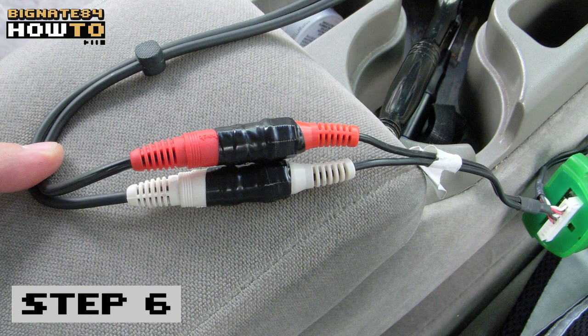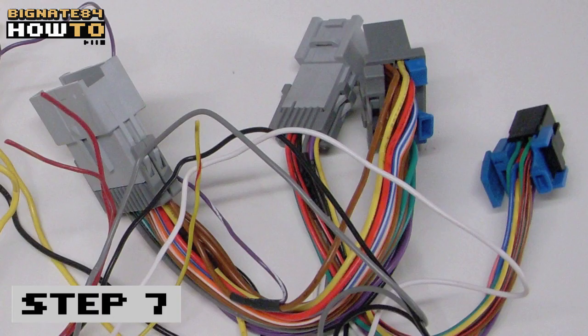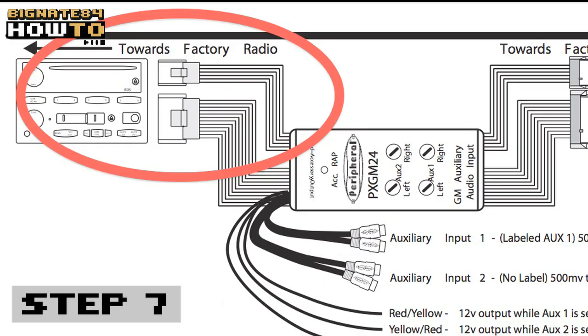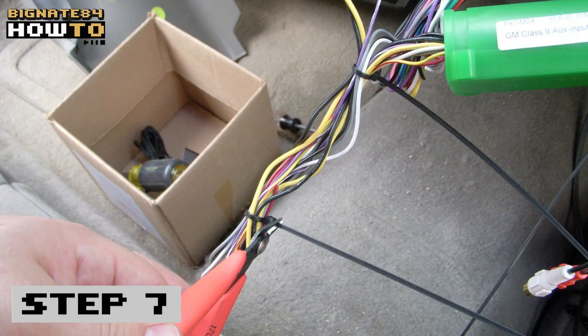Step 6. Connect the audio cable to the aux interface. I like to ensure a good connection by using some electrical tape on the RCAs. Step 7. Connect the auxiliary interface. First, plug the interface into the wire harness. Next, plug the other end of the interface into the back of the factory radio. It's a good idea to neaten up the rat's nest of cabling with some zip ties.